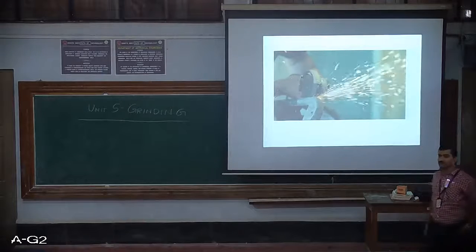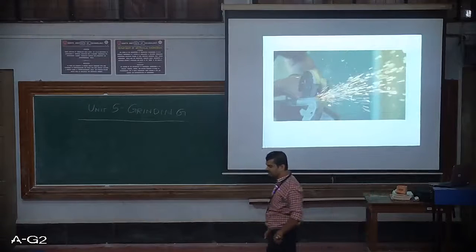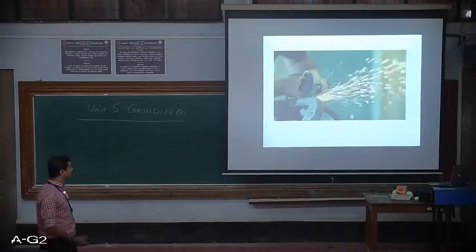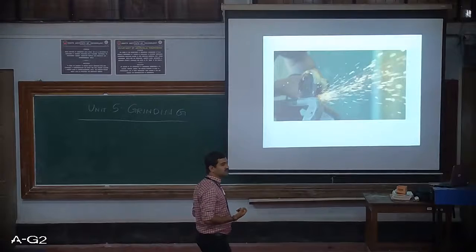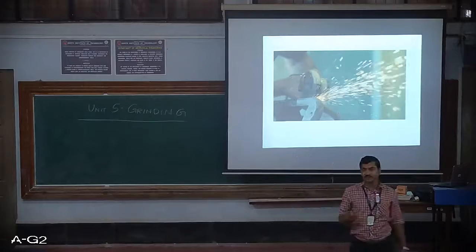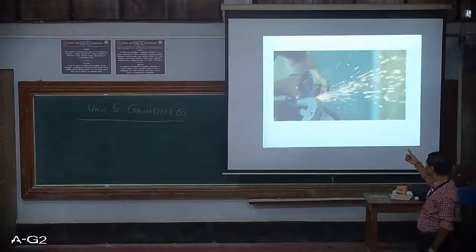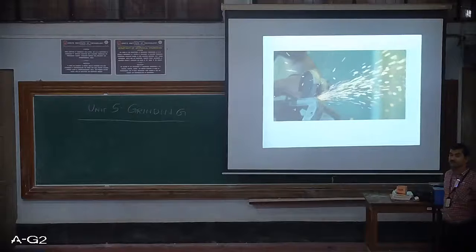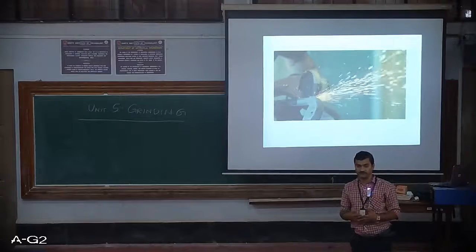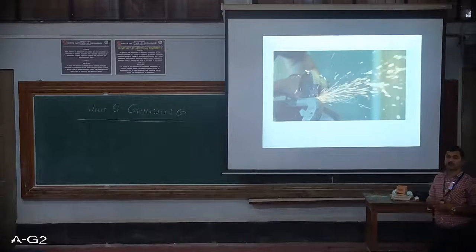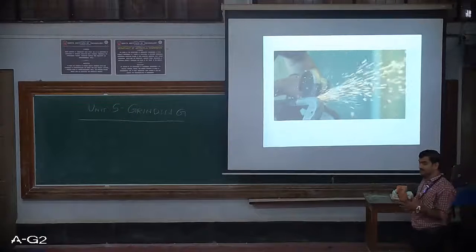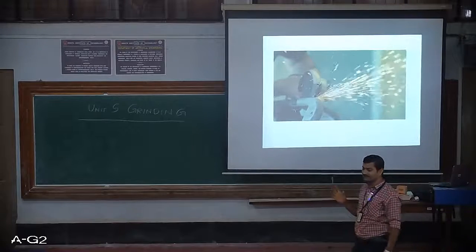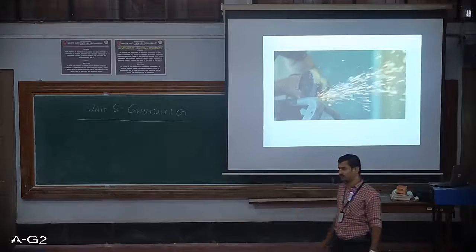Now next bit, this is what I was referring to. Here you can observe that there is a huge amount of sparks generated during grinding. If you see the speed of rotation of the wheel, the friction generated at the work tool interface is immensely high, and that is the reason so many sparks are being generated. That is why I had told you that we need to use excess cutting fluids in order to minimize the effect of heat, and that heat has to be carried away by the coolant. The coolant will be supplied at the juncture of the work tool interface, and that coolant will take away all the heat.